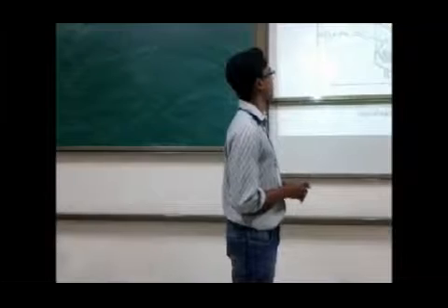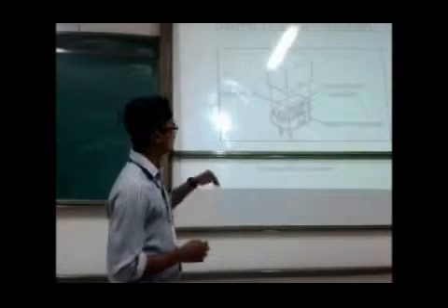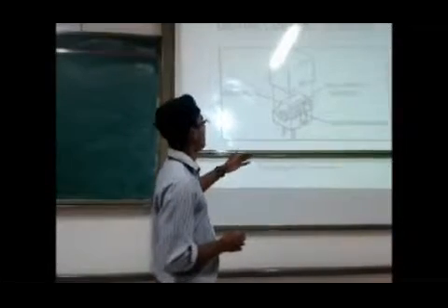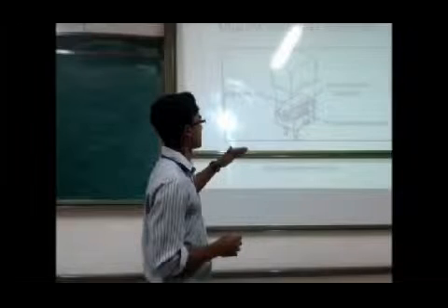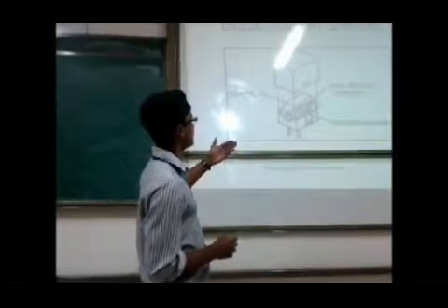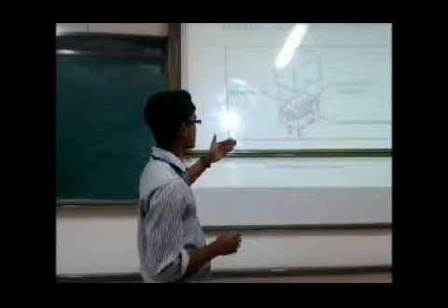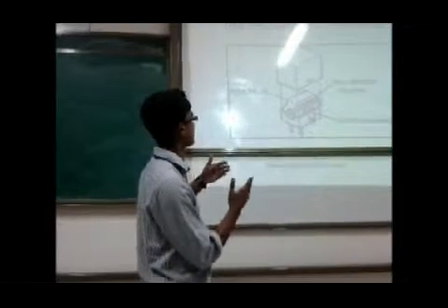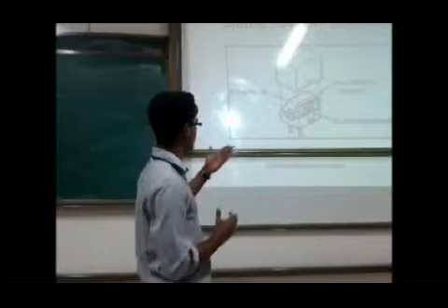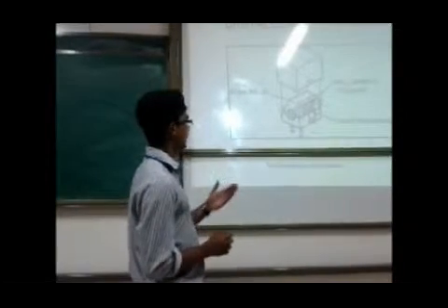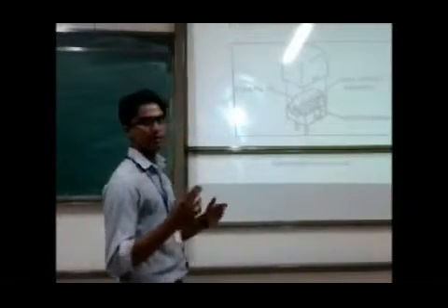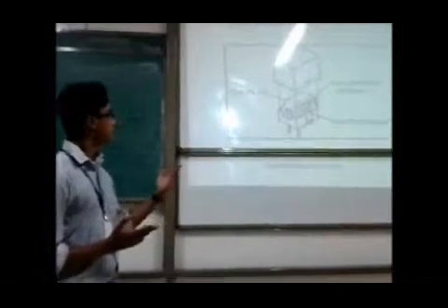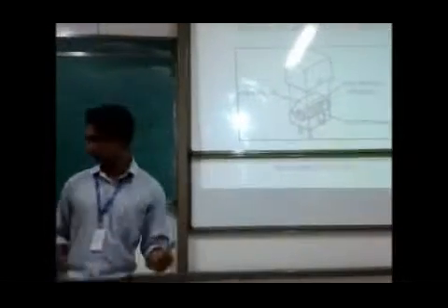So the function of the electromagnet is like this. Whenever a current is passed through the electromagnet, it will produce a magnetic field. That magnetic field will be sensed by the Hall effect sensor, so the magnetic field produced will give the amount of current passing through. The magnetic field is a function of the current passing through the device.